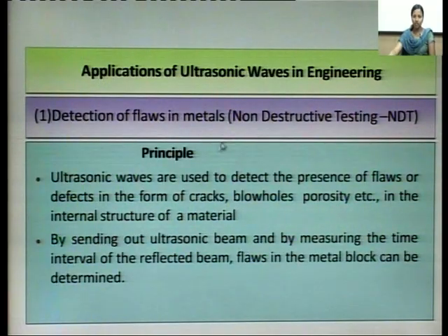This application is called non-destructive testing, NDT. It is based upon the principle that ultrasonic waves are used to detect the presence of flaws or defects in the form of cracks, blowholes, porosity, etc. in the internal structure of the material.